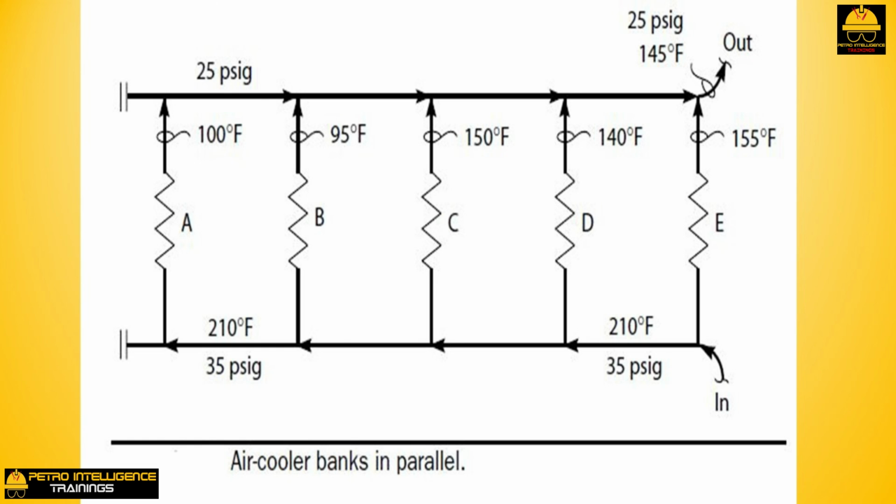5. Lower temperature favors the sublimation of ammonium chloride vapor to a white salt-like solid. 6. This salt is very hygroscopic, meaning that it will absorb and condense water vapor from the flowing hydrocarbon vapor stream at unexpectedly high temperatures. 7. The resulting wet chloride salts are very corrosive, especially to carbon steel tubes. 8. A ferric chloride corrosion product is formed. 9. This metallic chloride salt then reacts with the abundant molecules of hydrogen sulfide to produce hydrochloric acid and iron sulfide. 10. The hydrochloric acid may then continue to promote corrosion.